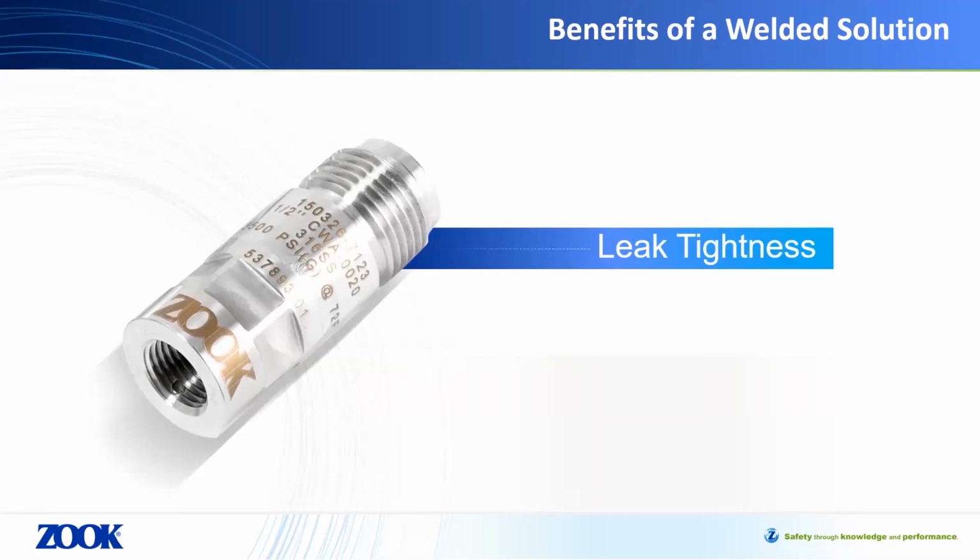When we talk about the leak tightness of welded products, we really take this to the extreme. Welded products have the ability to offer leak-tight hermetic seals that would only allow one 3mm bubble to make its way through any potential leak path over the time span of 27 years. When we're testing to these levels, we employ a helium leak detector as our tool of choice. This allows us to accurately measure and quantify leak test results in standard industry terms.